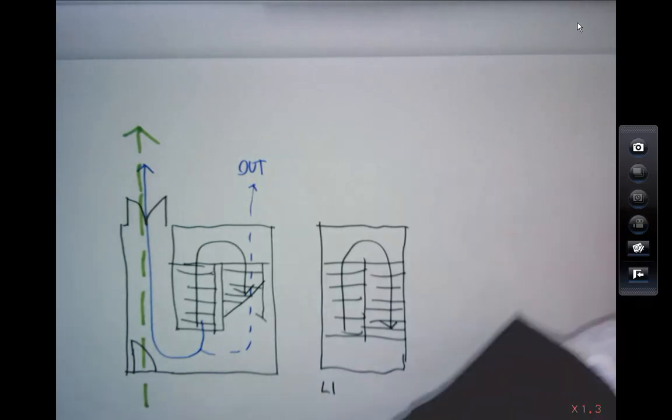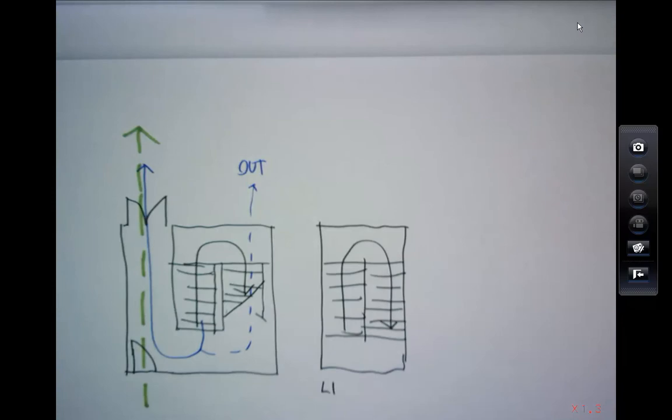Okay, how are we doing for time? Door direction. Don't get too hung up on that. You can have doors swinging in the direction of escape, as long as you have no more than 60 people, I think. I need to check that, actually. I think it's 60. All right, so don't think you always have to have your doors swinging in the direction of escape. You don't always. If you've got problems, you can get double swing doors that will swing both ways as well. Okay.